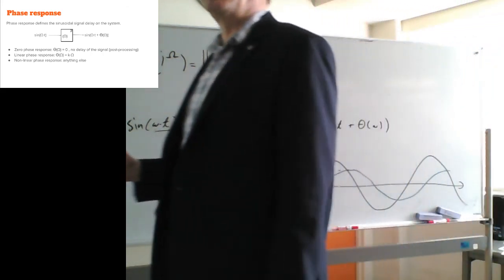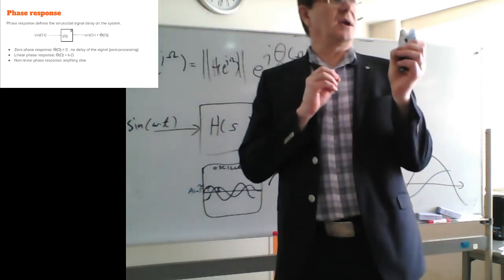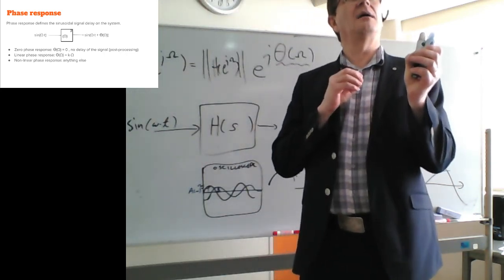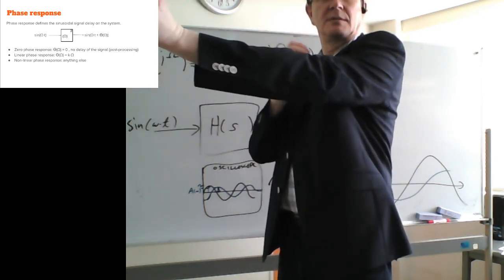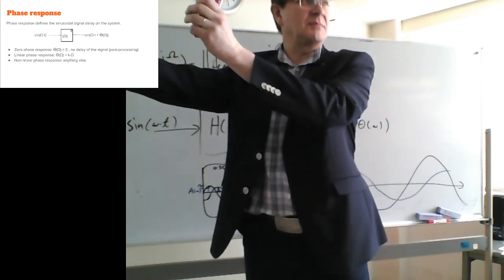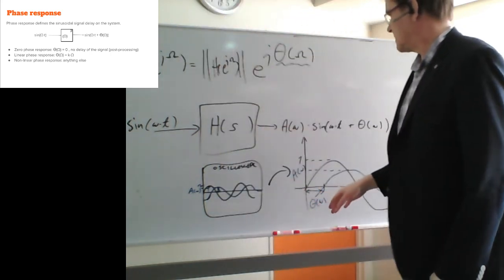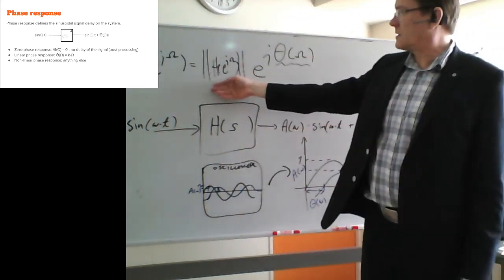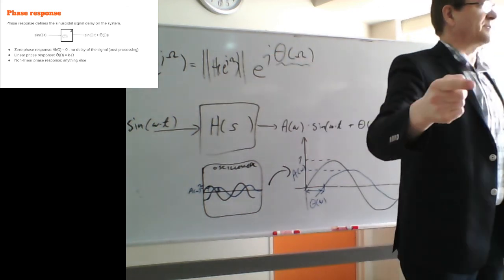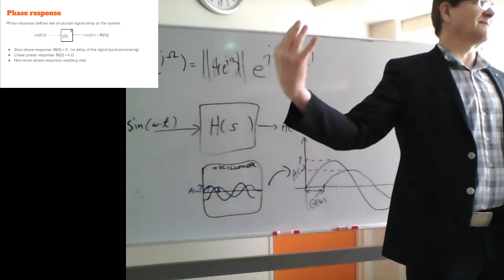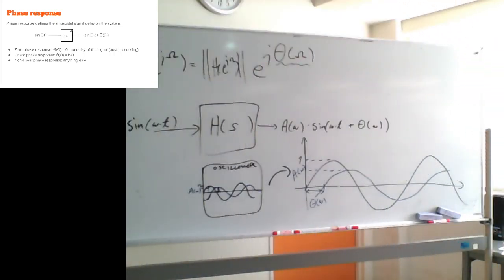The simplest way is basically take the data, filter it one way, reverse the time, do it another time. It actually doubles the effect of the amplitude response, but it also reverses the phase shift. Whatever the phase shift was, it's not anymore. It's 0.